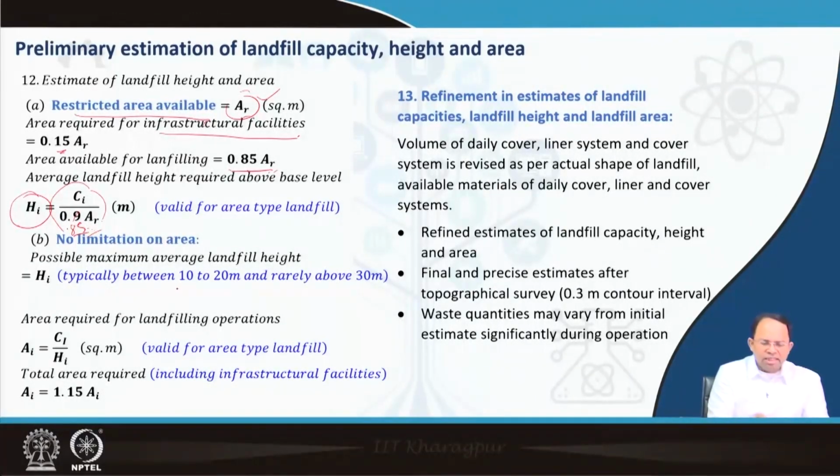So typically it is 10 to 20 meters, and rarely sometimes it goes around 30 meters, right? So typically we have landfills around 10 to 20 meters. So in that case, the height is more or less fixed. So we fix the height beforehand, right? There may be other aesthetic concerns and other concerns as well.